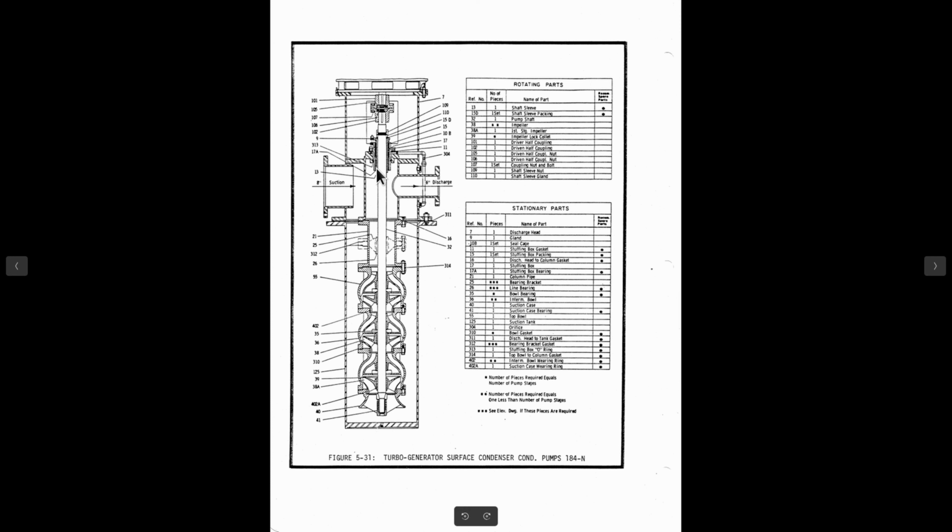Discharge here. It had packing in it. At first you'd use secondary loop makeup water to seal the packing. When you start this up, start pulling the vacuum, it could suck air in, so it was on the discharge pressure side, so normally it would self-seal itself. Here's the discharge line.